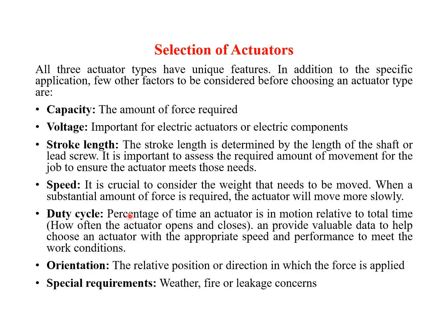When selecting an actuator, beyond the specific application, we should also consider certain other characteristics, that is the capacity, voltage, stroke length, speed, duty cycle, orientation, and also certain other special requirements. The capacity is nothing but the force required. The amount of force the actuator needs to generate to move the load or perform the required action is very important. And voltage: for electric actuators, the operating voltage is a crucial factor in order to ensure compatibility with the power source. And next is the stroke length.